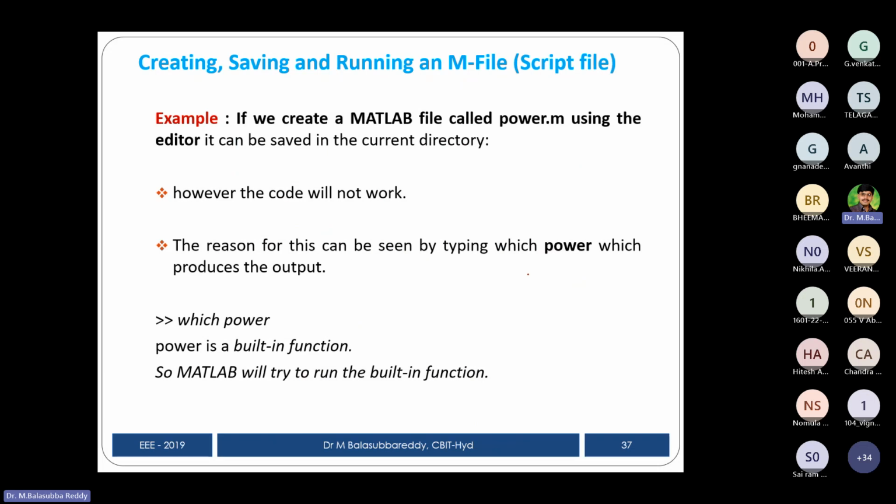Now we can see an example. Create a MATLAB file called power.m using the edit command. It can be saved in the current directory. However, the code will not work. What is the reason? The problem is the file name, power.m.